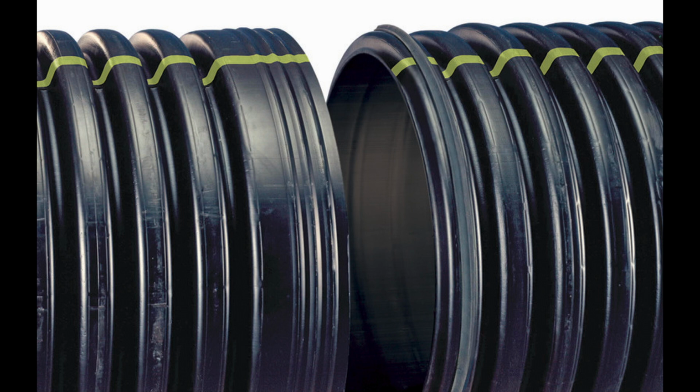I recommended replacing the 2 smaller diameter pipes with 3 sections of 12-inch diameter double-wall plastic pipes that would be joined together with gasketed fittings. A large amount of soil that is high in clay would be needed to cover the pipe and to fill the section of the dam that had washed out from water that was flowing over the dam.